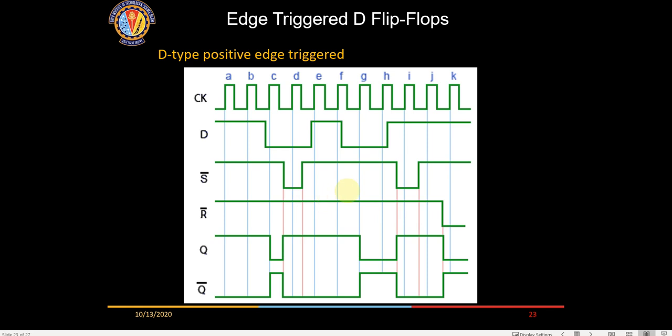Yeah, okay. See, these set and reset signals are not clock dependent. In this case, if you see, the moment the set has gone down, the clock has not yet come, but the output has straight away gone high. It is set bar. Set bar means if the signal goes low, the output has to go high. This is set bar. This is reset bar. Similarly, the reset is going down here. In this case, it is directly moving here, so it is as per the clock, doesn't matter.